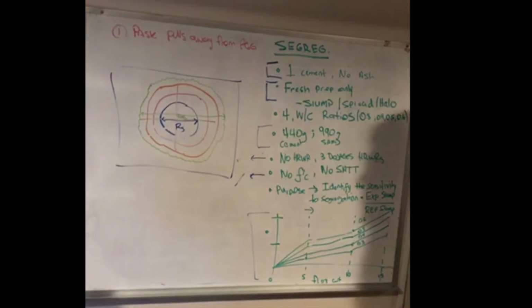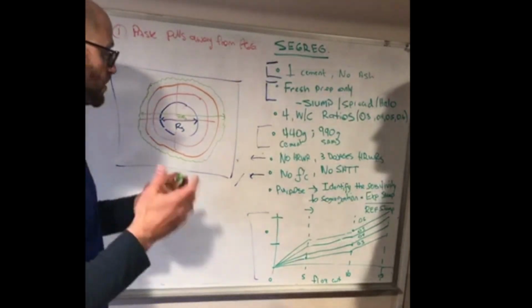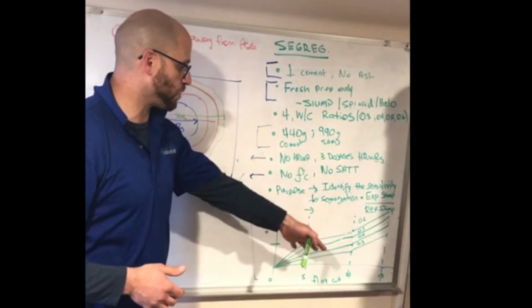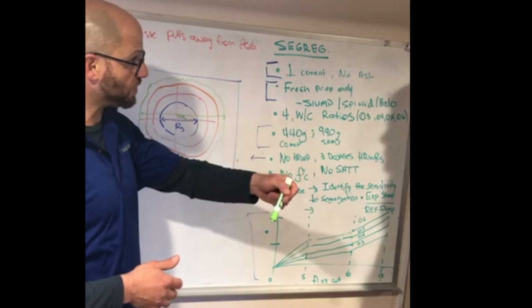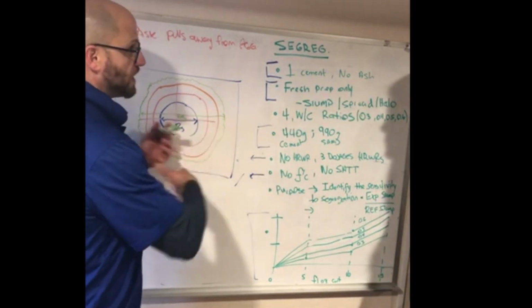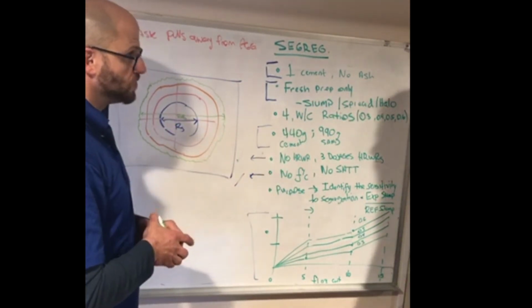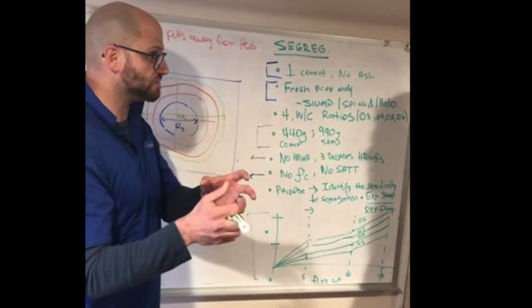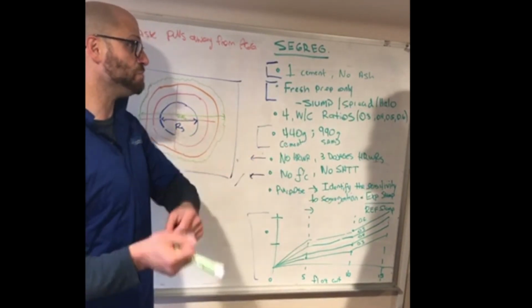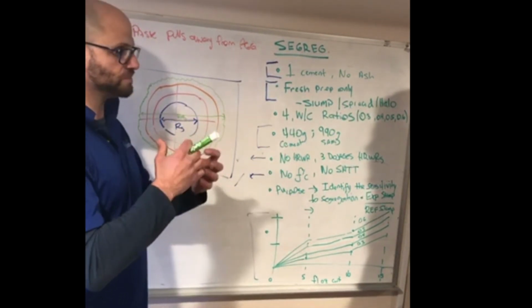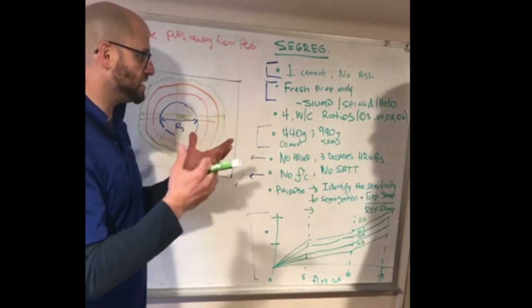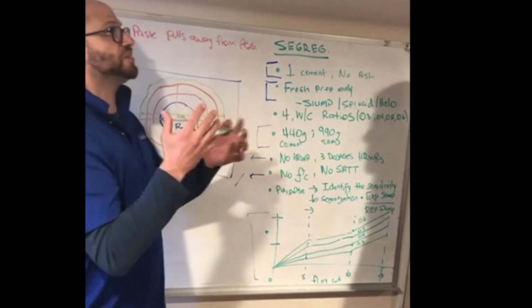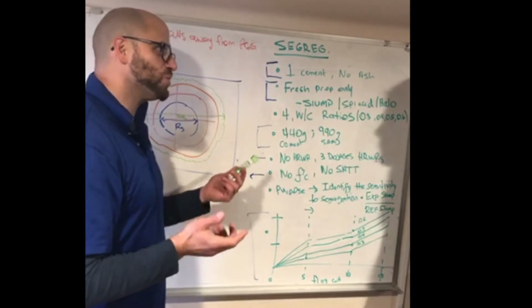Comparing those two will give us the ability to understand what that change in water cementitious ratio and high range water reducer does to that design versus actual. So to answer your question, it's the impact, not the actual segregation mechanism. It's not the rheology or the thixotropic nature of it, which are really great words.